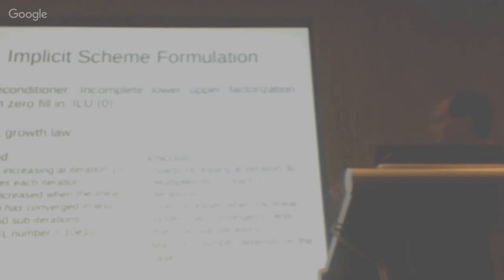So, okay, let's try to fix a limited CFL value up to a higher iteration number, then start to grow it slowly at each iteration. Whenever the linear system converges, you increase it. Otherwise, you keep it the same for the next iteration. But eventually, we found out that there is a stronger coupling between the maximum CFL number you can reach and the problem you're tackling.